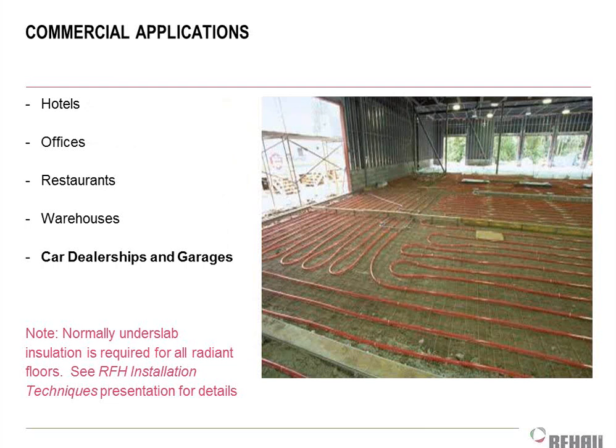Car dealerships, they don't like heating the air, right, because they're always opening the doors and the heat gets sucked out. So a lot of them have switched over to the infrared hanging heaters, which are fantastic because they shine down and heat objects, and they're heating up the ground as well. And then when you open the dock door, it doesn't go away. But the problem the infrared hanging radiant heaters have is they're heating everything they can shine on. Well, the one place they can't shine is underneath the car, right? And where's the technician at? Underneath the car.